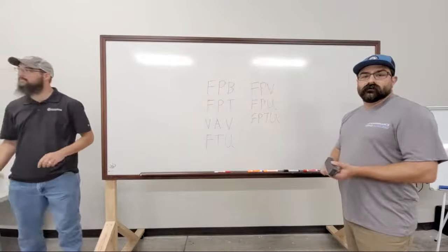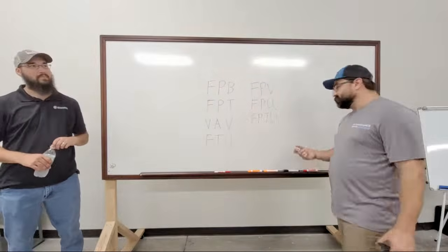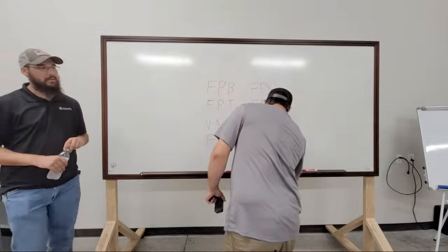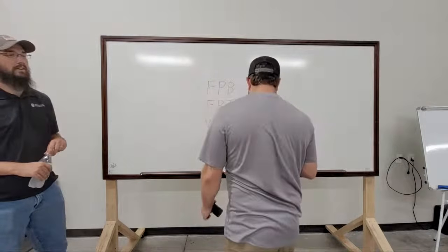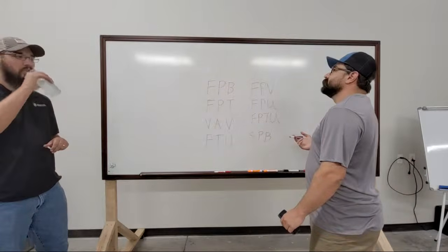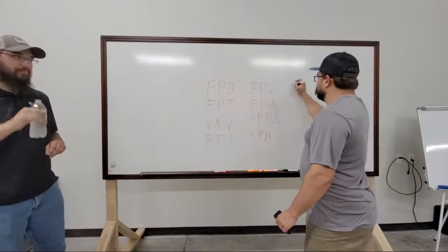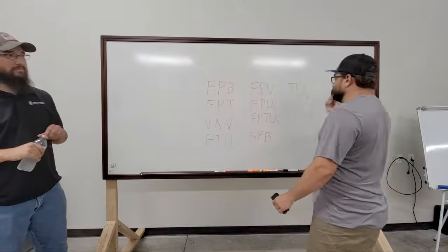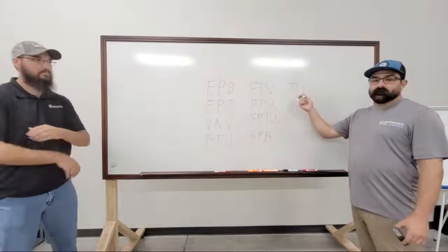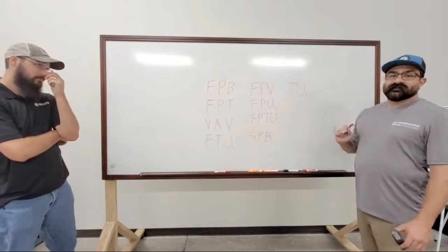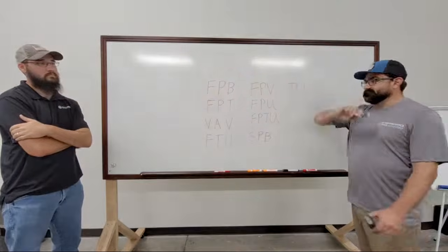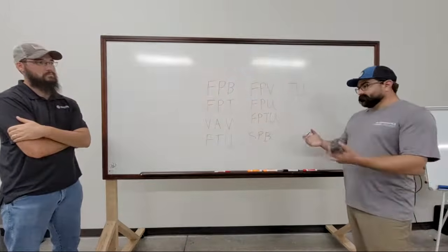Oh yeah, SPB. And then also, what else? Oh, it can be a TU as well, terminal unit. Heard them labeled that. That one can be really confusing because we have one building, everything's TUs. Fan power boxes, VAVs, doesn't matter. They're all TUs because they're all terminal units.